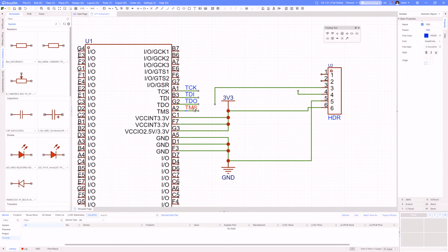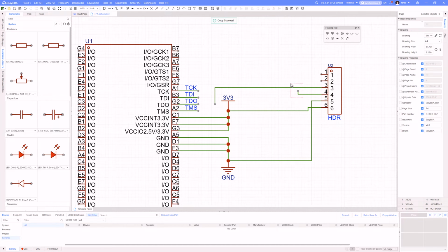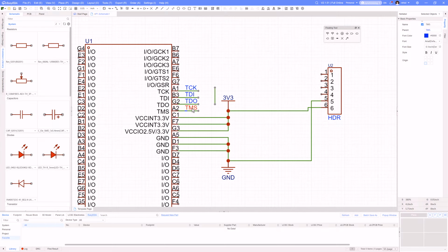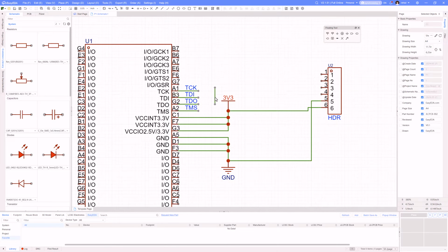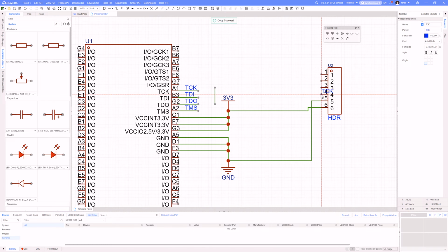And then I can turn around and, if I choose just the label, I can copy paste it and say, okay, let me get the rest of these lines out of here. Copy paste, Control C, Control V, and say, okay, I wanted on the bottom TCK. So let me grab TCK here. TDO, TDI, and then TMS. So this will essentially say that these are the same network, so these are going to be connected. That's another way to do this.